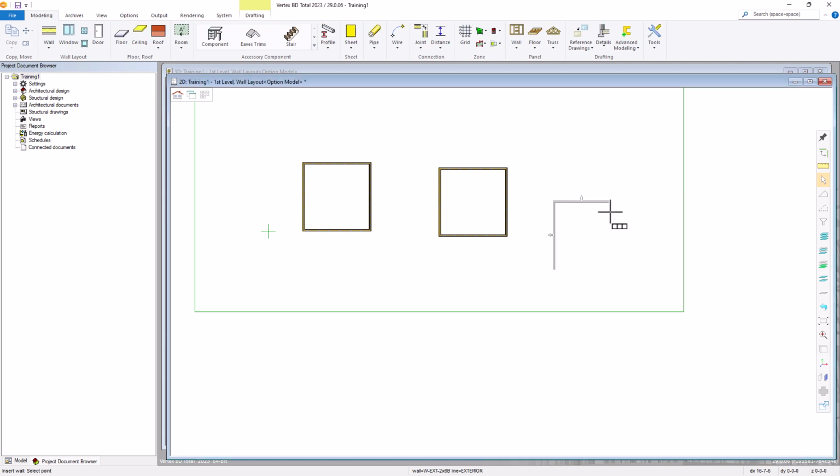And when we move over to the right, you'll notice that the constraint has already been set. So it alternates between vertical and horizontal. So now I'm going to go over 20 feet again and pull it down. And you see that it's locked again, 20 feet, and go to the start point. So that's a nice feature that will help to eliminate some keystrokes.